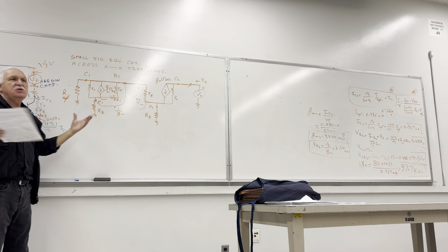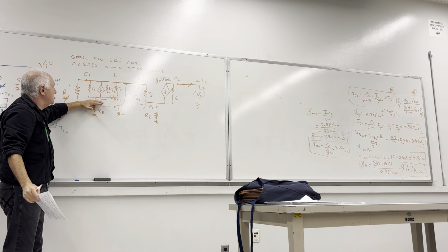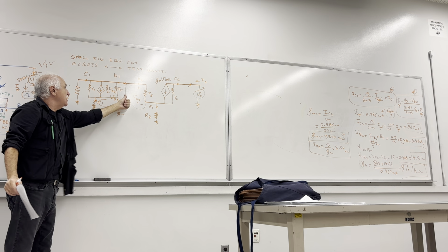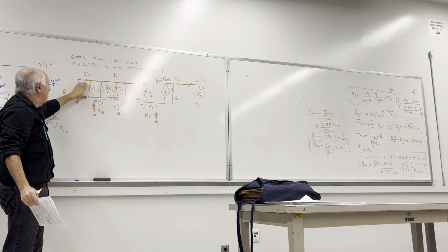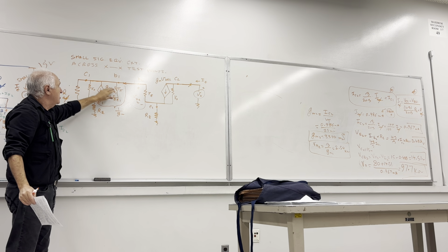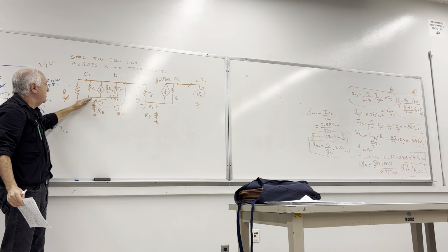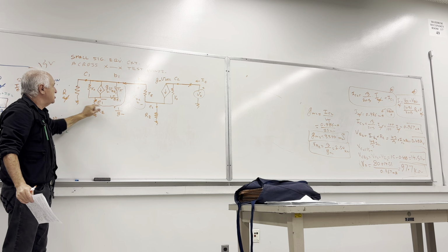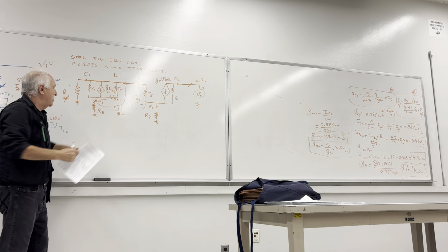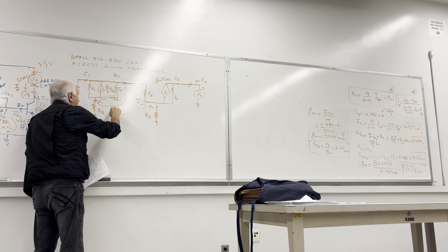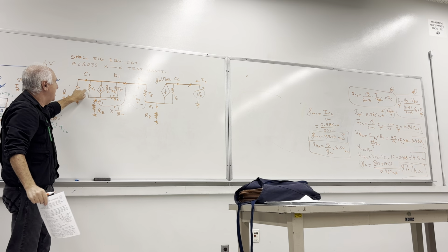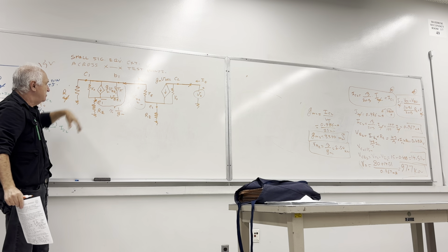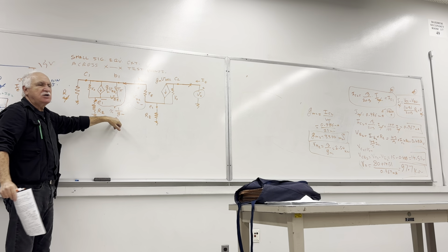Simply, you've got to cut the circuit from here, calculate input impedance of this assembly, RF, RO, GM, R pi, and you will end up having impedance from X to X approximately 1 over GM. That R pi won't count. So it's approximately 1 over GM.